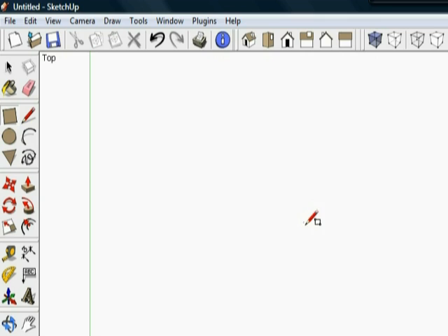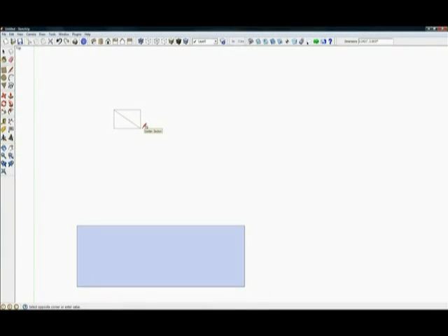Now I can draw a square, and you see I've got a reference there. I'm getting, what would I call that? The dotted line that's going from opposite corners. You'll see I've got a rectangle there, and if I keep going down, now I've got another line there. And these are representing degrees. I have SketchUp currently configured to snap in 15-degree increments, and I can show you that. Here I know that this is based upon a 15 degree. There's another that should be popping in here somewhere.